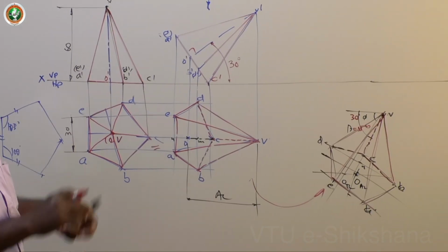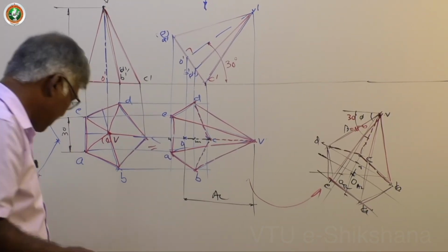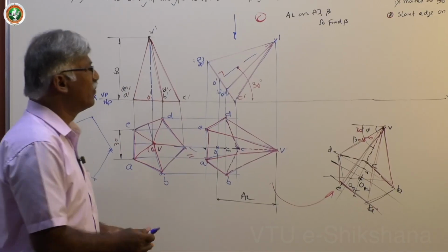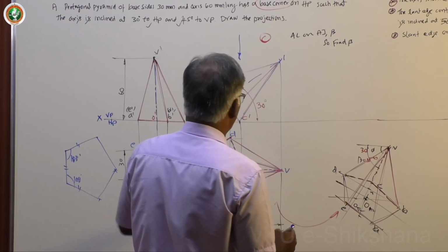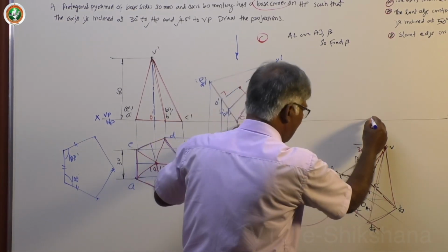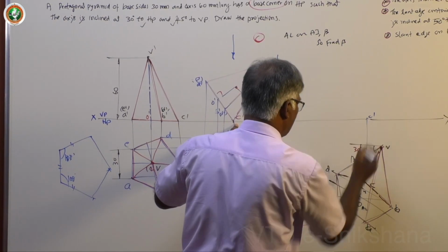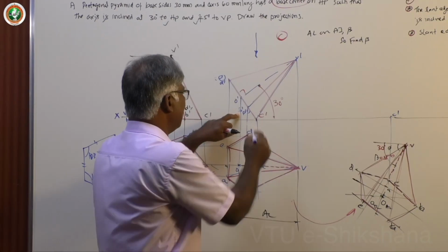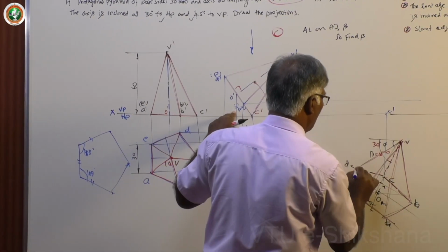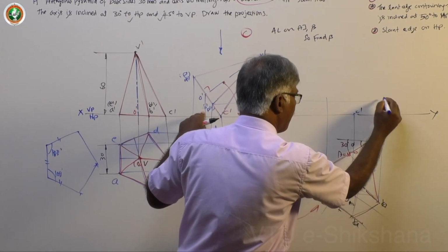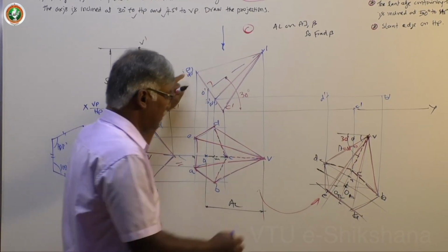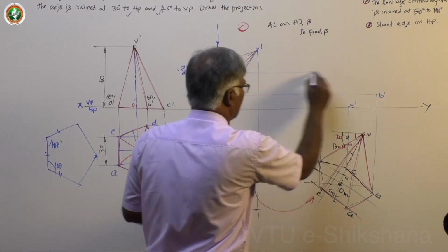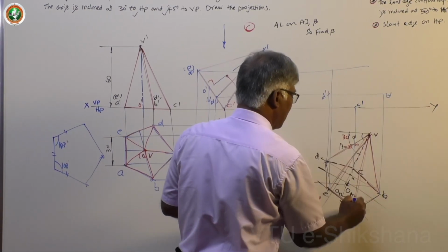So now you project it up towards the front view and get all the points ready. Now let me mark C exactly on the XY line because it is on the ground, C dash. Next points are B and D: this is B dash, this is D dash. Then A and E; unnecessary lines you can avoid.